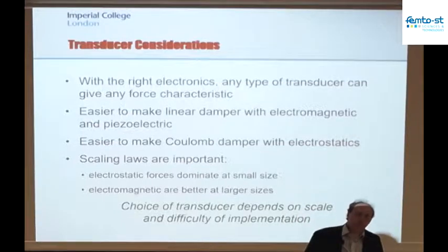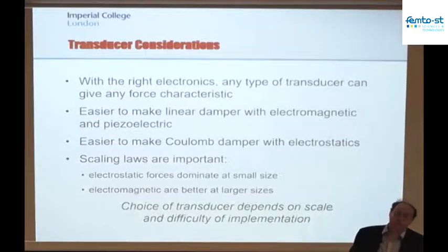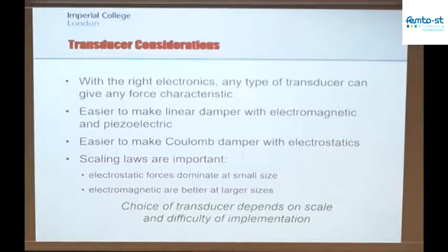Most of these systems that we're talking about for energy harvesting, certainly motion harvesting, are going to be producing sinusoidal outputs. If it's piezo or electromagnetic, it's going to be producing an AC waveform. We've got to rectify that to be able to power any modern electronics from it. And that's one of the sets of requirements. But the other set of requirements is not looking forward to the electronics, but looking back to the harvester. How do we get the optimal force on the harvester to maximize the power density? And that's also something that the electronics should be able to do.